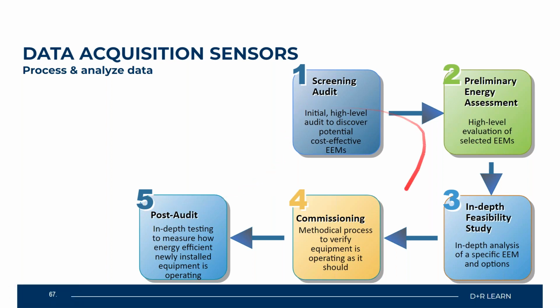So this 5-step process here, you'll pretty much find this happening with any type of system that has a BAS system, and a lot of equipment that has been in use for 15, 20, 25 years plus. This is a great way of evaluating those systems through the logs, through operation, and then through your utility company making recommendations for upgrade of the facility components. And then from there, your post audit will actually show you what you have in energy savings.